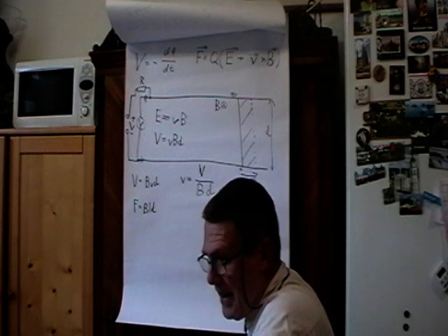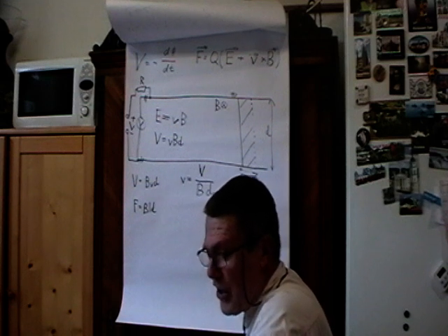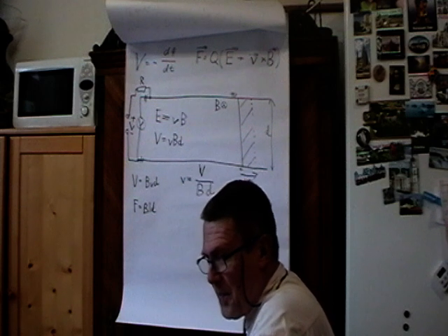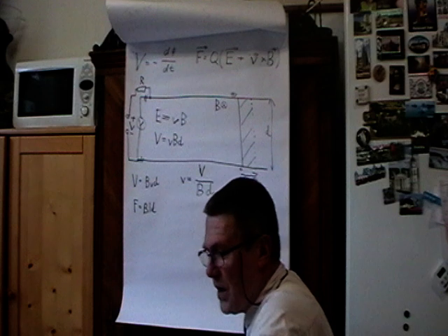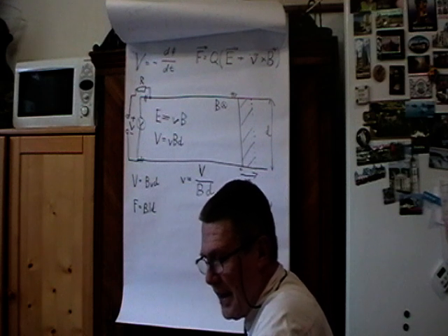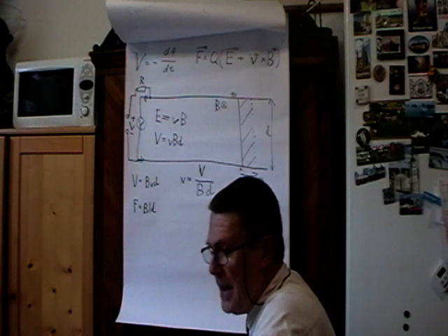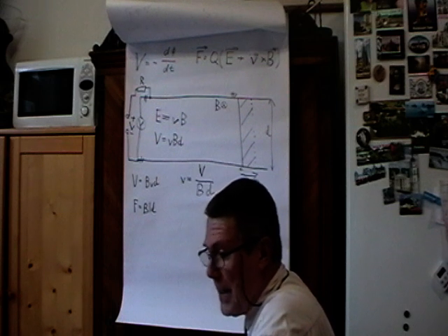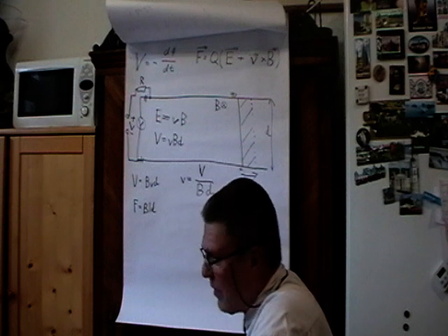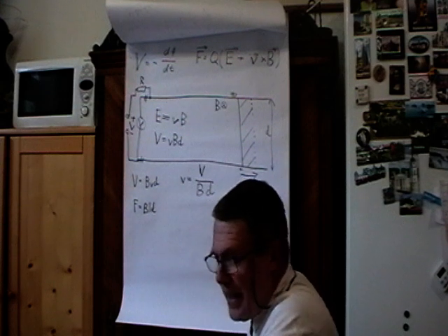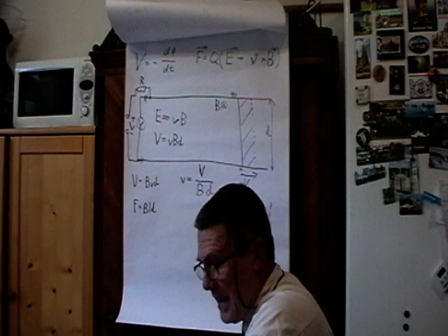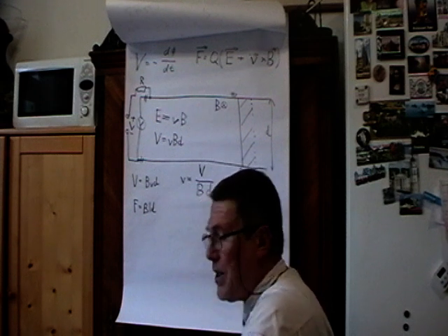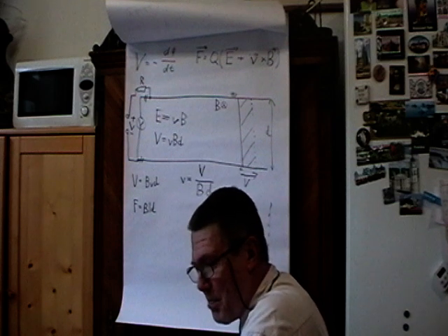This is the trick that is done in traction cars like trams and underground: you control not only the voltage feeding the winding, but also the voltage that creates the magnetic field. And if the motor is not overloaded, if you are not running uphill, you can decrease the magnetic field in order to decrease induced voltage, in order to increase the maximum speed.